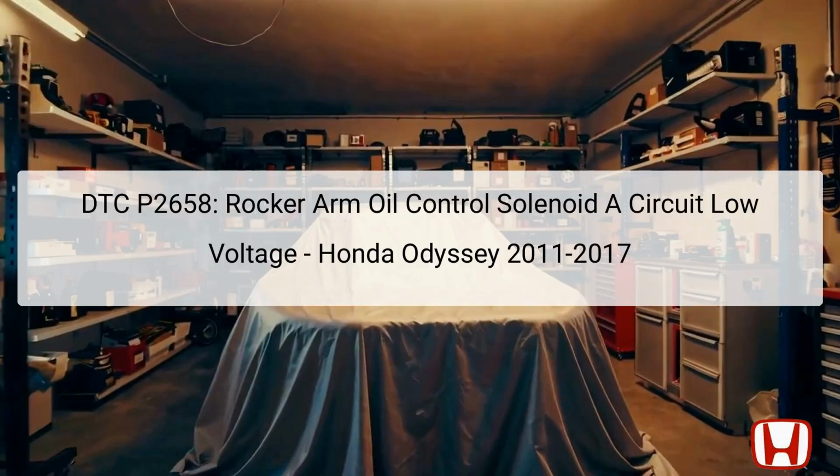The diagnostic trouble code, DTC P2658, refers to an issue within the rocker arm oil control solenoid A, specifically for Bank 2 in the Honda Odyssey models ranging from 2011 to 2017. This code signifies a low voltage condition within the electrical circuit of the solenoid, which is crucial for the VTEC, variable valve timing and lift electronic control, system operation.